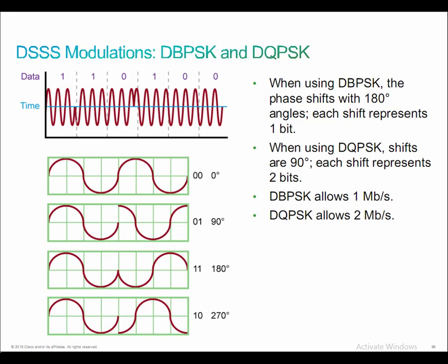It works very well because the rhythm of the transmission is known. 1 digit is sent each microsecond. So we're not talking about within a 1 second period. We're talking about microsecond periods. So 11 digits get sent in parallel. The receiver only needs to listen to the shape of the wave for the next microsecond to know whether the next value is a 0 or 1.